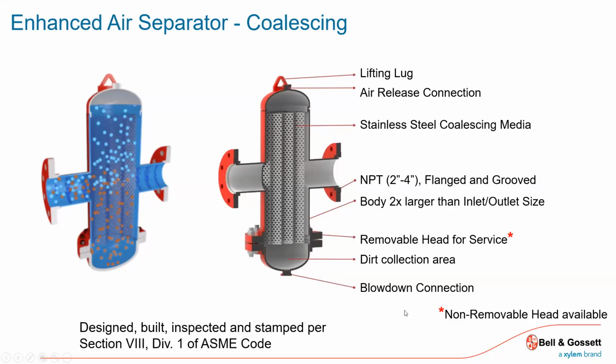But if I give it enough surface area, all of these small little bubbles will gather and they'll become bigger bubbles, literally. And then inside this lower velocity, lower pressure chamber, they will be released out through a high capacity vent at the top. So I've got all of this surface area here to collect any of those air bubbles that are coming in, big or small, gather on this media, and then eventually be buoyant enough and get released. Very popular, very common in commercial application.